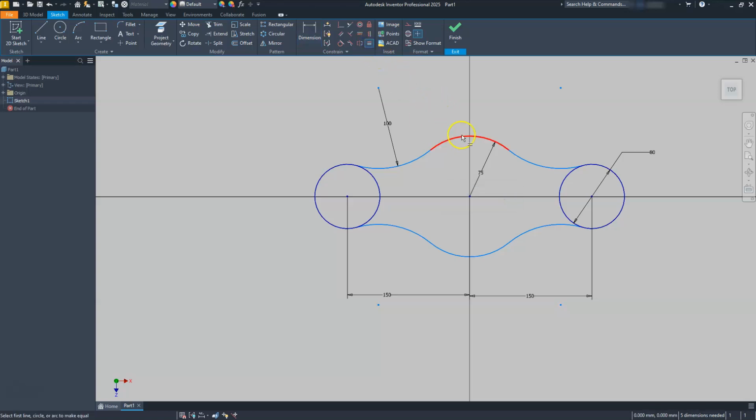and then I'm just going to equal this one to this one, right? And it seems that once I broke that, it also broke all of these equals between here. So let's go ahead and put that equal back. Just going to put an equal to these. Oh, seems like it's already there. Okay. So it must be missing its tangent then. That'll be the next thing I'll try.